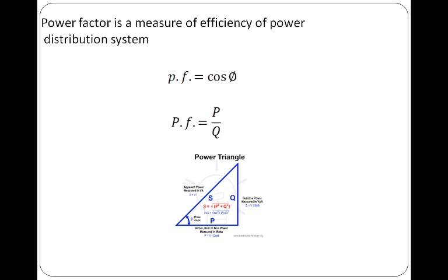We have said reactive power does not transfer energy, so it is represented as imaginary on the vector diagram. Real power moves energy, so it occupies the real axis. We have talked about the units: watts for real power, VA for apparent power, and VAR for reactive power.